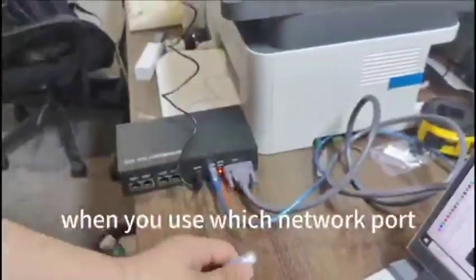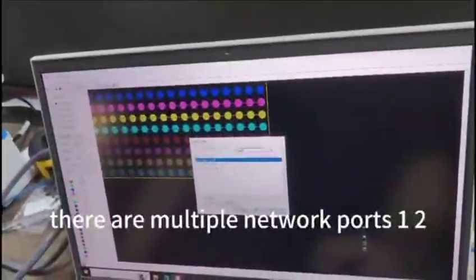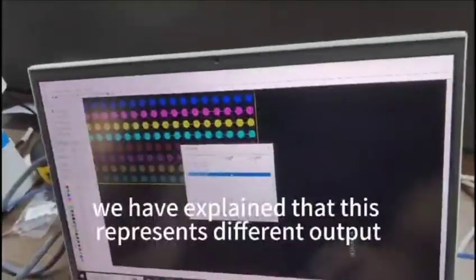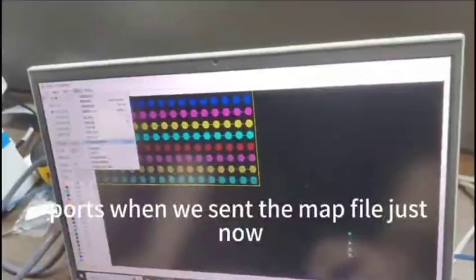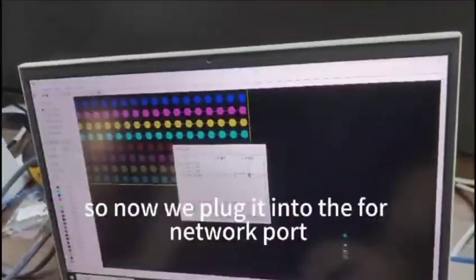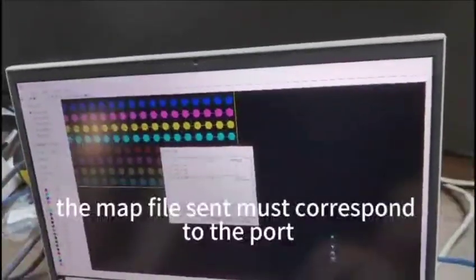In fact, when you use which network port and draw the LED pixel map, you need to connect the corresponding network port to send the file. There are multiple network ports 1, 2, 3, and 4 here. We have explained that this represents different output ports. When we sent the map file just now, it was connected to the 4 network port. So now we plug it into the 4 network port. In other words, the map file sent must correspond to the port.